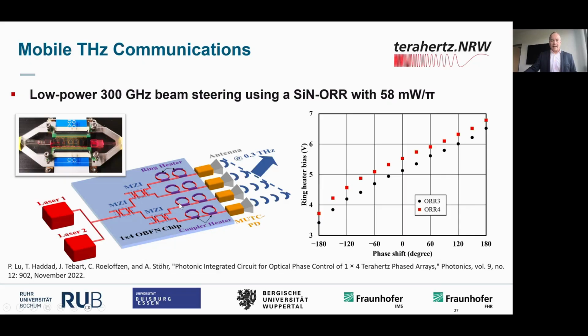It contains a number of phase shifters and true time delays. So we are able to delay the signal of the data to the individual photodiodes. We have basically a phase array at the output of this chip, so an array of photodiodes with antennas, and we can delay the time at which the data signal arrives at one of the photodiodes, and that allows us to steer the beam.